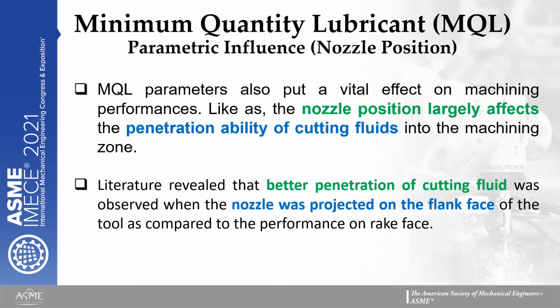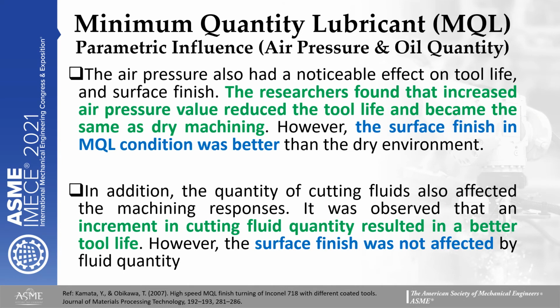The performance of MQL technology is linked with different parameters. One such parameter is the nozzle position, which largely affects the penetration ability of cutting fluid into the machining zone. It is observed in the literature that better penetration of cutting fluid was achieved when the nozzle was projected on the flank face as compared to the rake face of the tool.